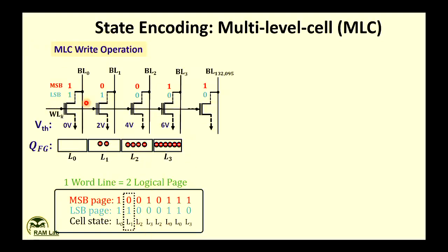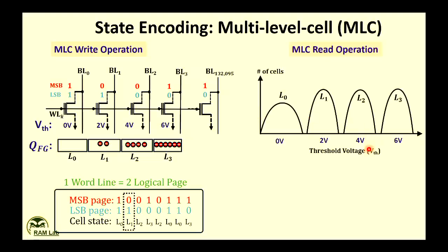Now suppose I want to do computing between these bits. What should I do? This is the question. Computing will be done just through read, right? You saw either multi-row activation read, multi-word line activation read, or single word line activation read. Here you have to do single word line activation read, which is the default de facto mode for any memory chip. So this is the way you will do the computation. To understand computing read, first we need to understand normal read.